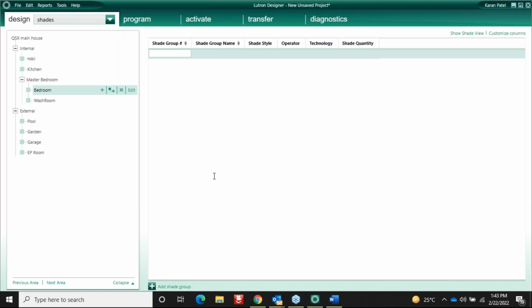In a project, if we don't know the load type, like forward phase or reverse phase, then what do we select as the load type? You have to go to the specification sheet of the lights. Read the specification, and first thing, if it's an LED, you can start with the LED reverse phase, because most LEDs work with reverse phase, and see the dimming performance. If you are not getting proper dimming performance, then change to forward phase and try. But you need to know what the load type is.